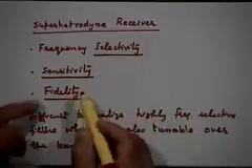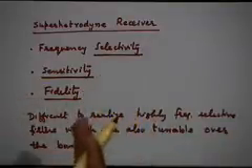Of course, fidelity would simply require that the bandwidth of the filter should be sufficient to pass the message without distortion. So if it is a 15 kilohertz bandwidth signal, over the 15 kilohertz you do not have a lot of variation in the frequency response of the filter, either in amplitude or in phase. Of course, phase distortion is not very important in voice applications, in music applications, but it is fairly important in, let us say, TV applications, picture applications.